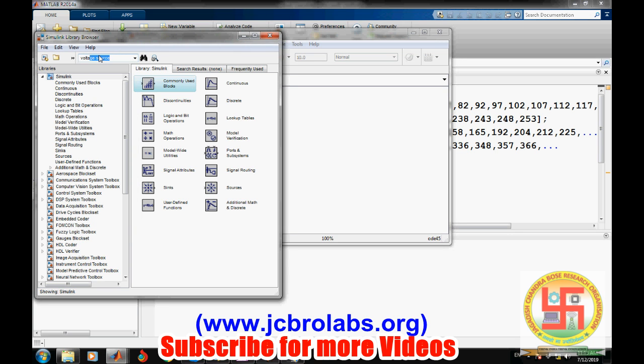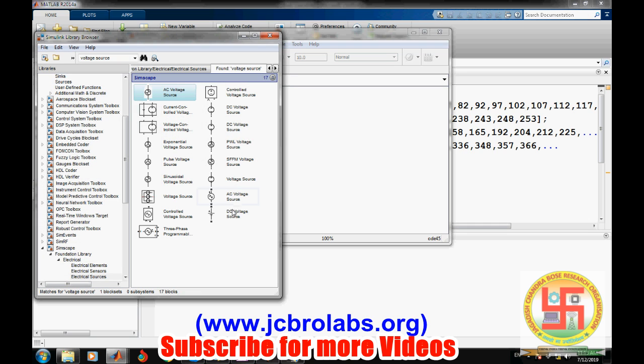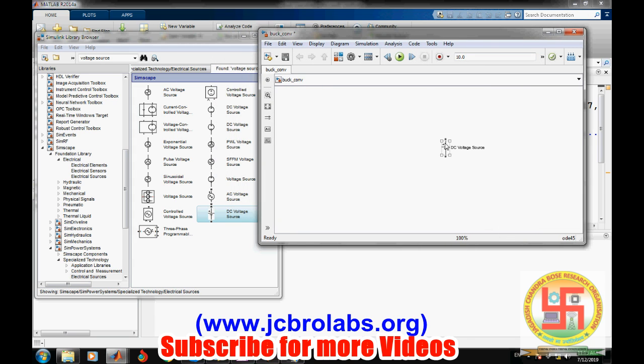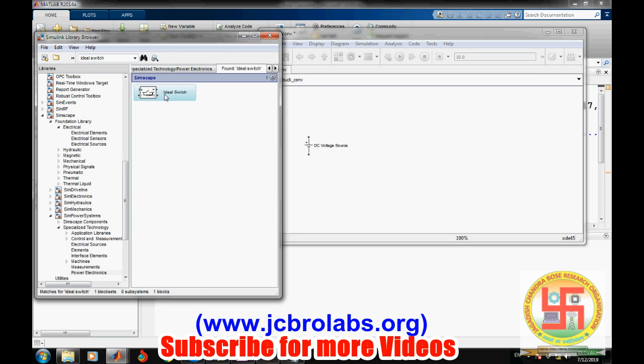Okay, we need a voltage source. There are two categories of models: power system models and the SimScape models. These power system blocks don't connect with the SimScape blocks, so you have to be careful about that. All the blocks which we will take from the Simulink library will be power system blocks, the Sim Power Systems. So we have our DC voltage source, and then we need a switch, so we will take an ideal switch.